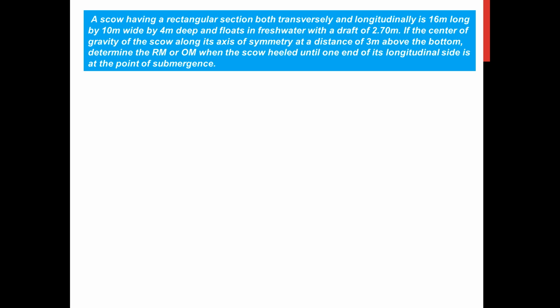If the center of gravity of the scow along its axis of symmetry is at a distance of 3 meters above the bottom, determine the righting or overturning moment when the scow is heeled until one end of its longitudinal side is at the point of convergence. So we have to determine whether your couple will be righting or overturning moment.